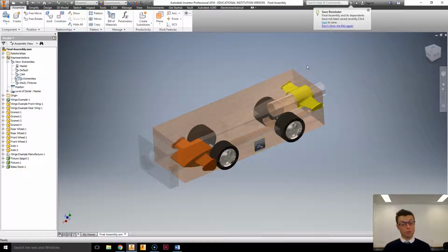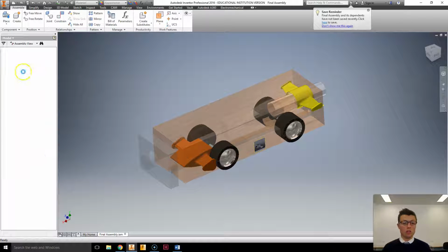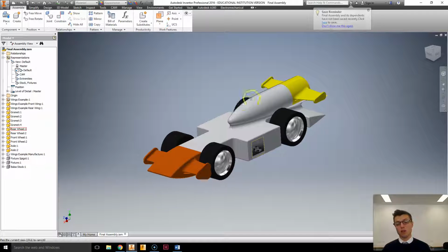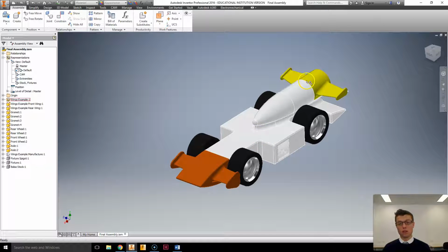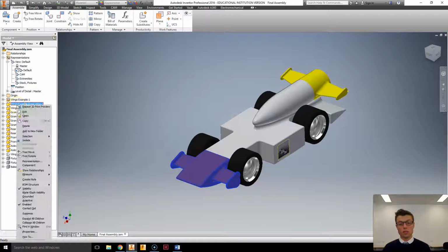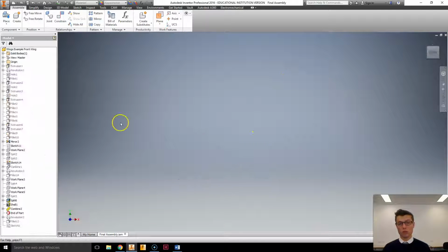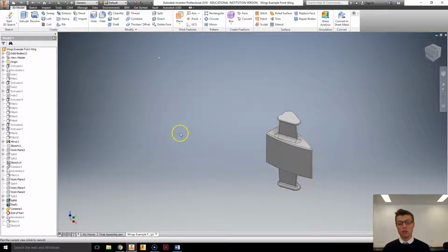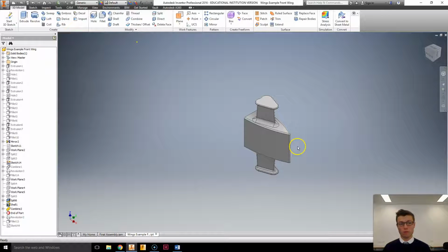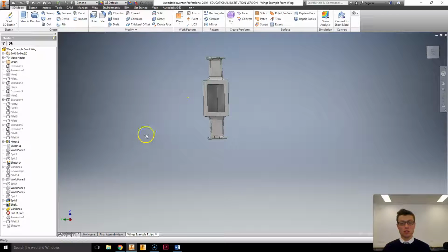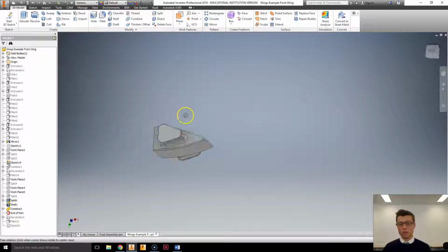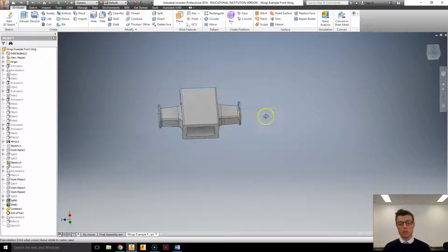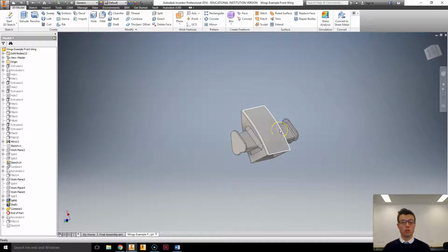Alternatively, and this would be my suggestion, from the assembly file where you can visualize and you've collected everything and you know that it's all the right shape, you would want to select one of your wings, right click and go open. You could also alternatively find the file in your workspace. Now, having selected that file, make sure that nothing has changed from your design, that it is actually still accurate and the one you would like to create.